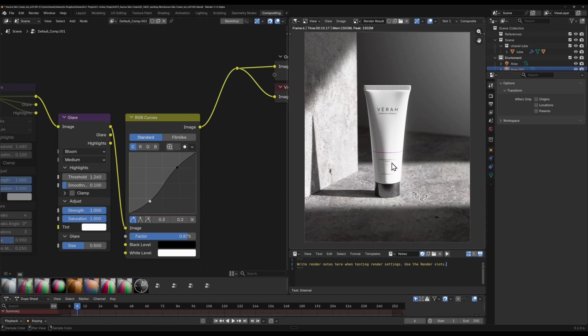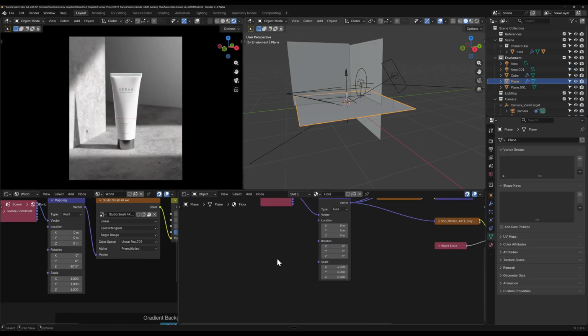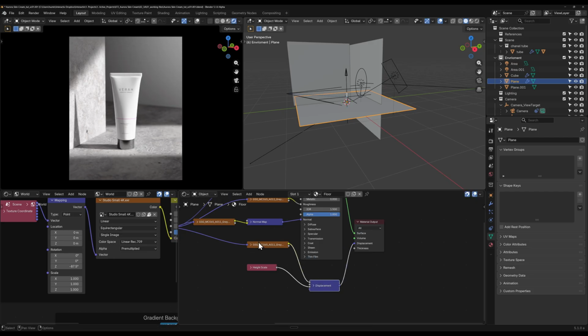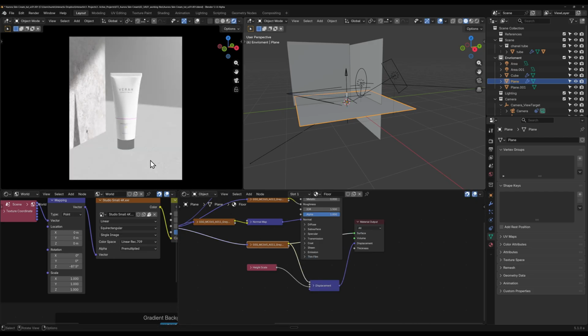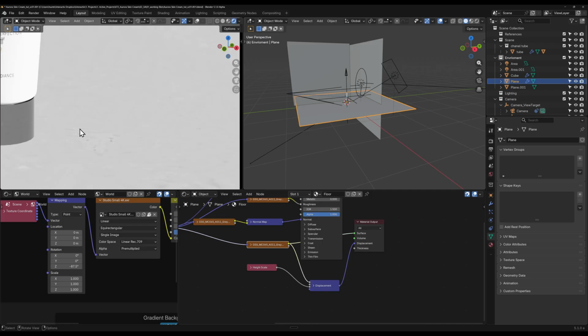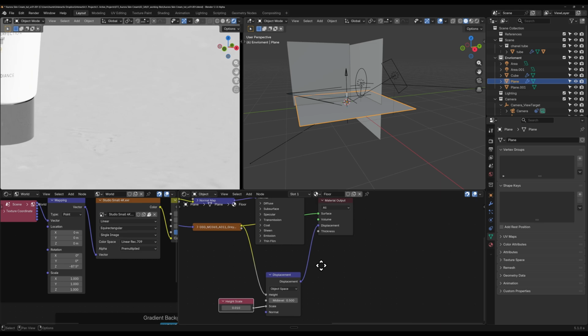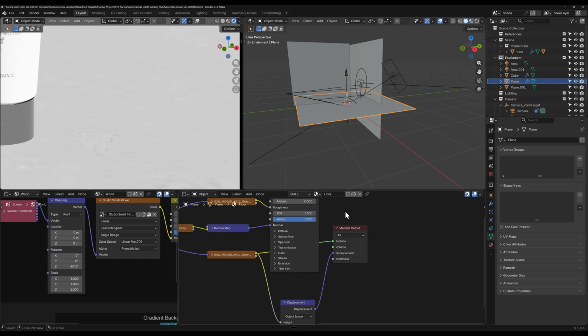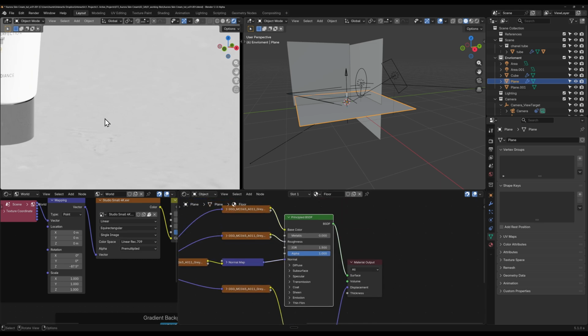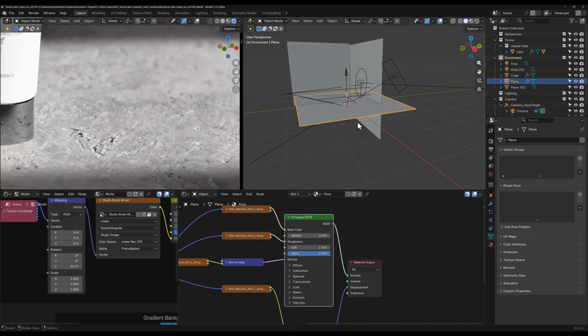So there's a render. Now it is the displacement on the Grayscale Gorilla texture. So if we go back here, this texture here, right? It's got displacement. So this is what this looks like. So it's got displacement map in the Grayscale Gorilla texture. And so this is what's creating our immense detail in our scene in the concretes, along with adaptive subdivision. So you see how detailed that is?